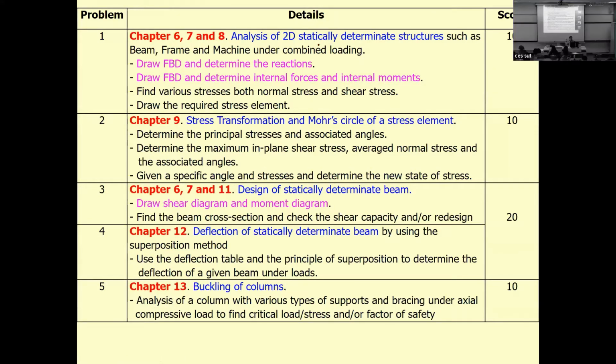Okay, we will have the equation sigma equal to force over A. That's going to start with chapter 1. Okay, and also we will have chapter 6. That's going to have the equation of sigma equal to M y over I, the moment times the distance y, divided by moment of inertia. We will be talking about this later. And the other one, chapter 7, is going to be talking about the transverse shear, tau equal to VQ divided by I t.